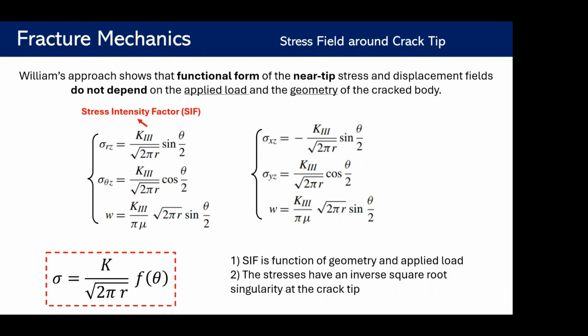The final solution of the problem, I mean the stress field and also the out-of-plane displacement W, is given by these equations here for third mode, in polar coordinates and also in Cartesian coordinates. The most important thing for us in this class is the functional form of the stresses and displacement field around the crack. This solution is the dominant term of the Williams expansion.